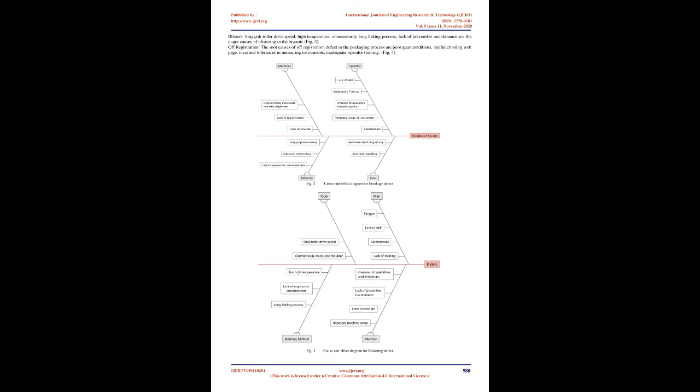Biscuit defects: breakage, blisters, cream oozing, hard bite, shrinkage, reverse shell, and biscuit spreading. 2. Packaging defects: off-registration, met layers, sealing defects, pinholes, underweight packages, overweight packages, and loose packaging. These defect types include 7 biscuit defects and 7 packaging defects, 14 in all.